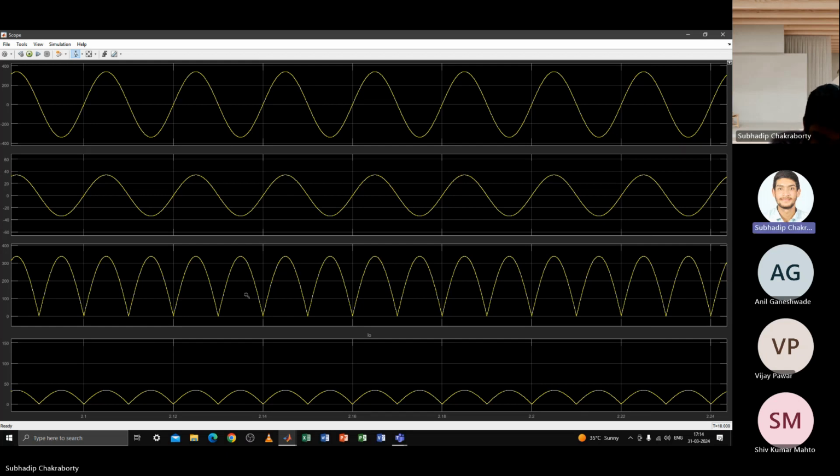Because if voltage doesn't have any harmonics, as you see, then the current fundamental will only contribute to the active and reactive power. So first you determine what are the steps. First you determine the fundamental component of the current, and then you see how much is the phase shift. From that you can apprehend what the phase shift means in terms of angle. Then cos of that angle of the fundamental will give you the active component of the current, and sine of that angle will give you the reactive component of the current. Hope this is clear, right?